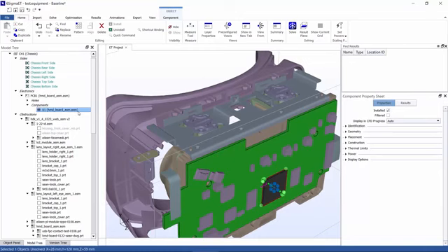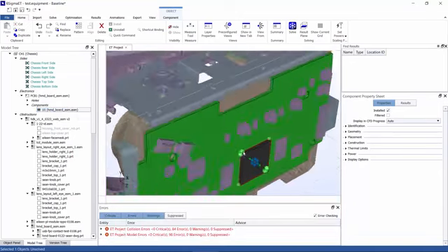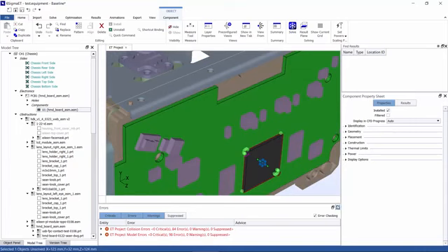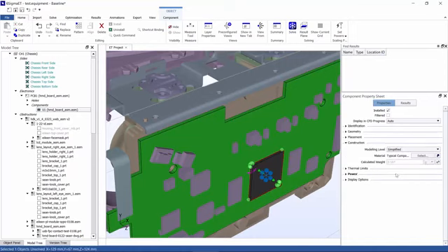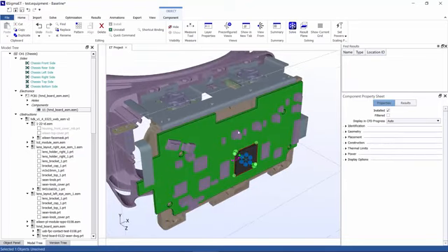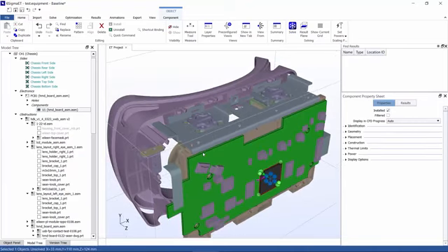And you'll see in the model tree that this component has actually been automatically attached to the board because it saw that there was a board nearby and it said, okay, then that must be a component, and it attached it. And so now, if I were to go in and move this PCB, the component would move with it, and it also inherits any other properties as well. And again, everything is fully parametric with this component, so it can be changed in the property sheet. So this process can be repeated for the rest of these components, or you can group select them or use the find tool and select them and convert all of them into components. And now you have a fully native PCB with components that is fully parametric to be adjusted just with a few clicks of the mouse.